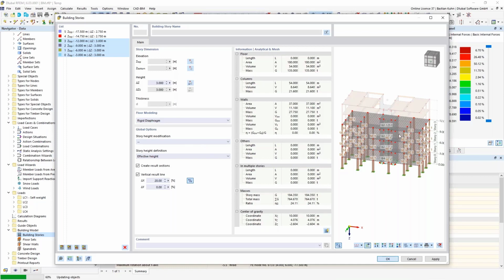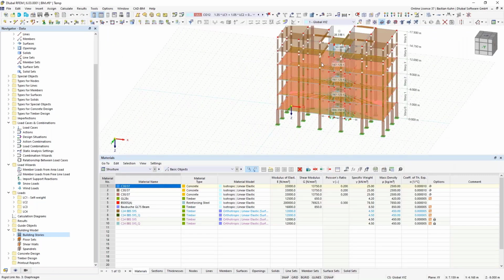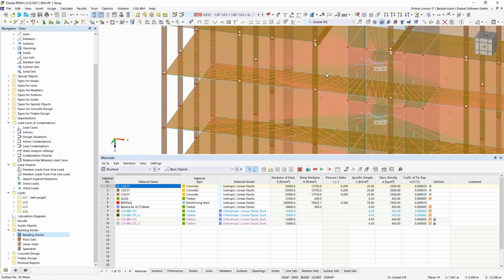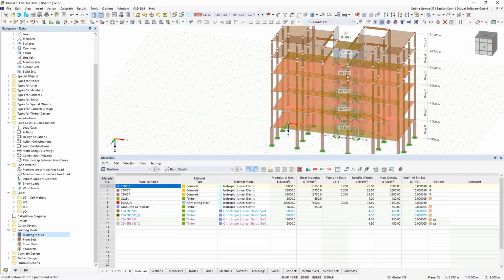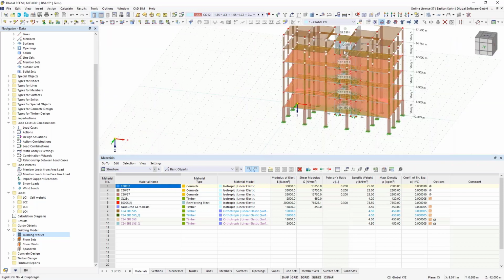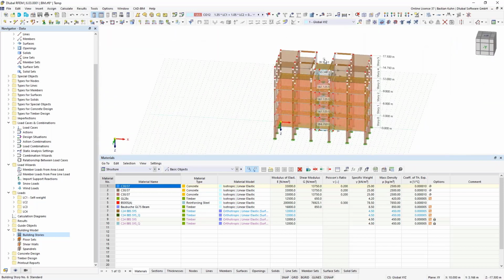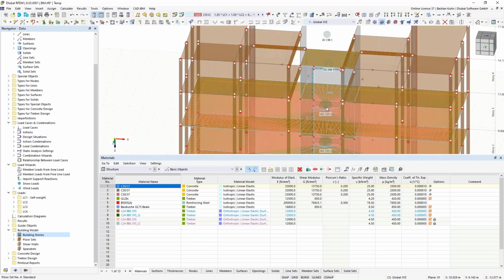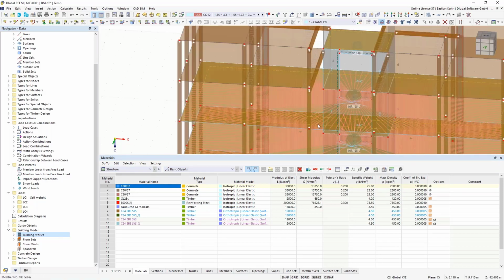And now when you press OK, it's deleting all the results. And now you see here a lot of red lines, I would say. These are rigid couplings which go from, and you see a blue bubble in here. So the lightest one is on the top story, 28.59 something tons. And then, okay, concrete is the heavier material. It goes up the more down you go. And these red lines, or these rigid couplings, are centered in this mass center, and they are connected to each of the columns or each FE element in each story.